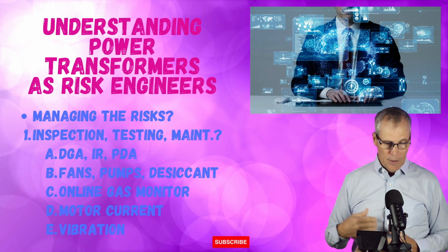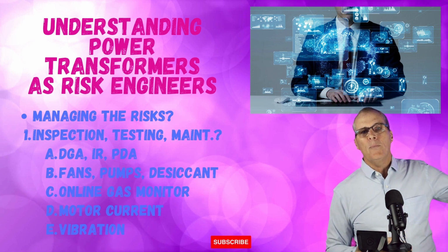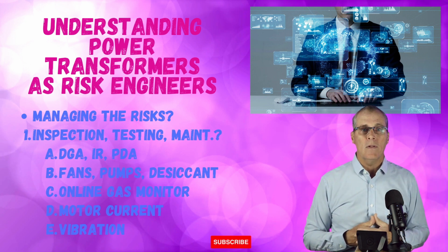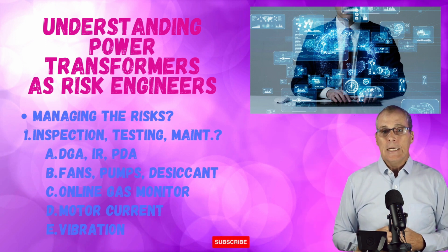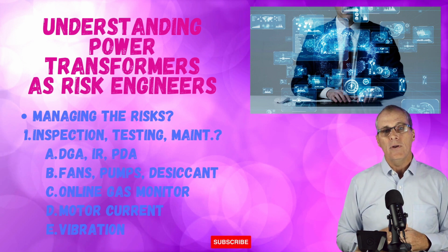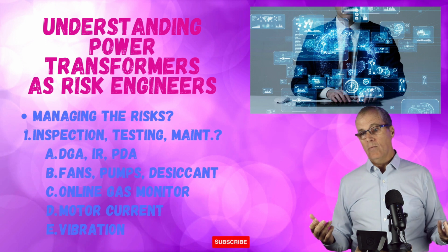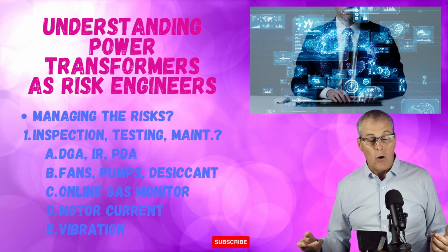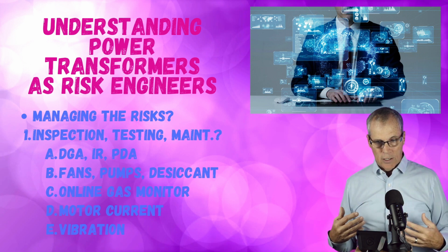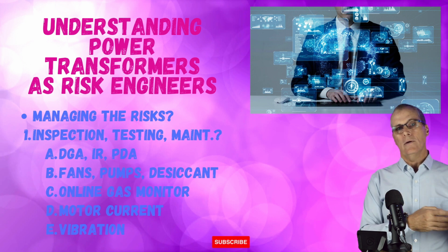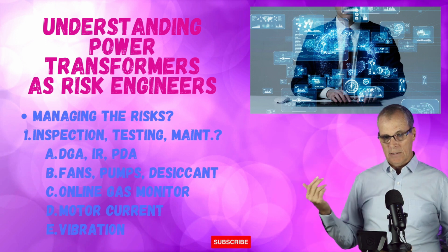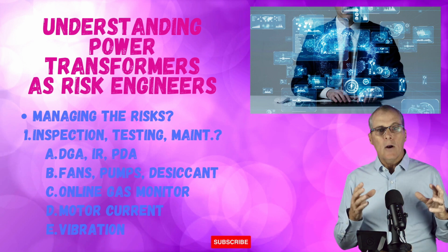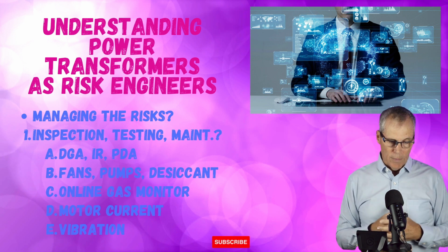Nothing happened. But one day, a big steel company out on the system has a ground fault and your plant trips offline. Your transformer protects the plant, the breaker's open, and now you decide, well, did something happen? We could do sweep frequency response analysis, SFRA. That's a technique where they inject a signal, look for a reflection of that signal, and see if it comes back the same way it went in. If it didn't, they know they've got a problem at that frequency. Anyway, they've got a way they can look into it, but that can cost a little bit of money and it can take a little bit of time.